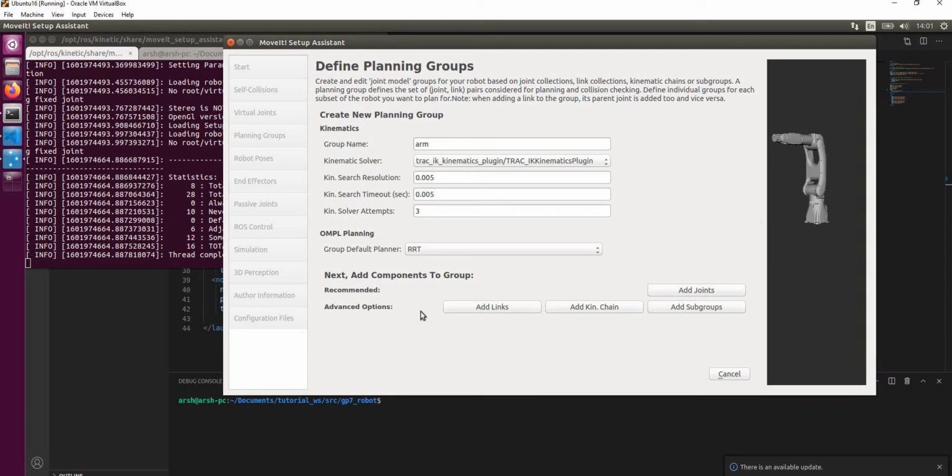There are different planners. Each planner converts these poses into inverse kinematics, and from the inverse kinematics it checks that joint 1 or joint 2 are not out of their limits and so on. One of the fastest, and in my experience the one that almost always works, is RRT. I'm not sure what it stands for, but do look it up.